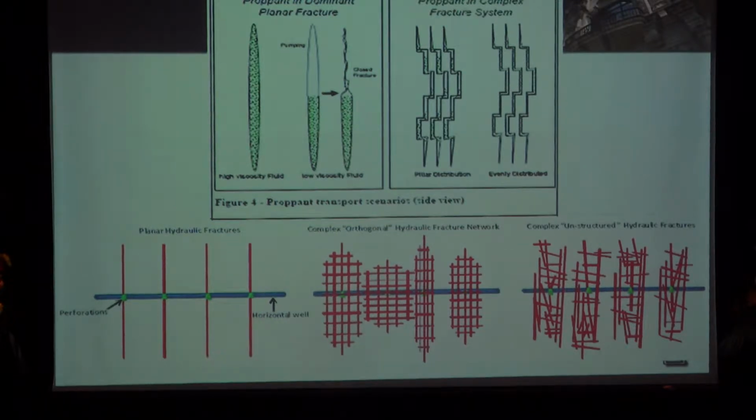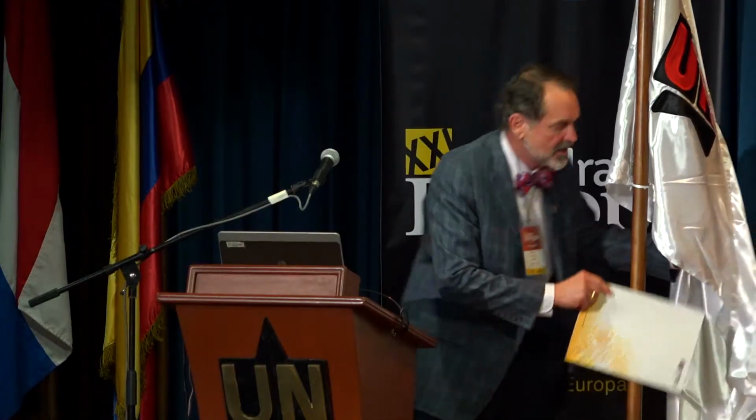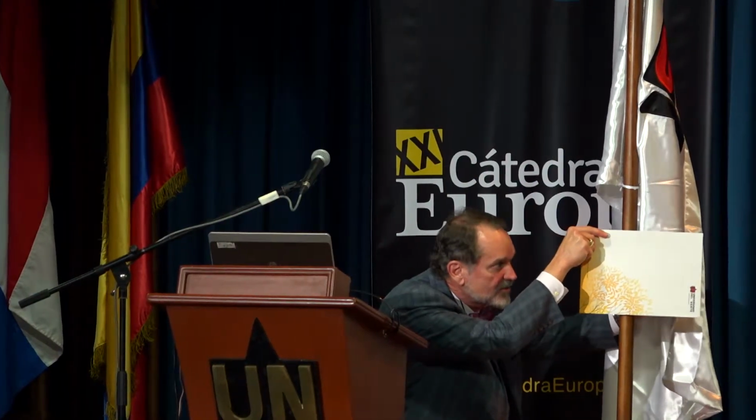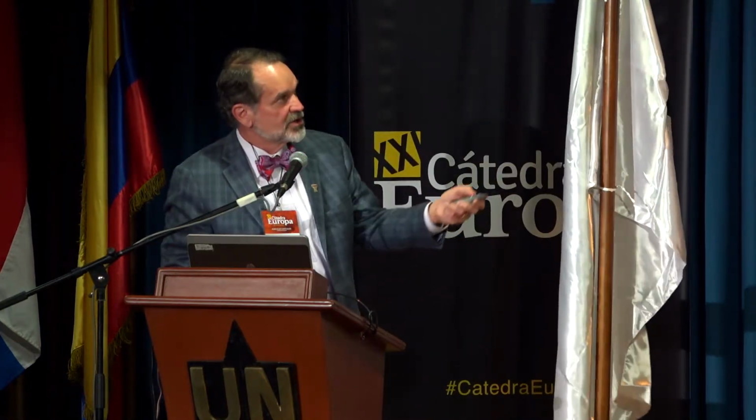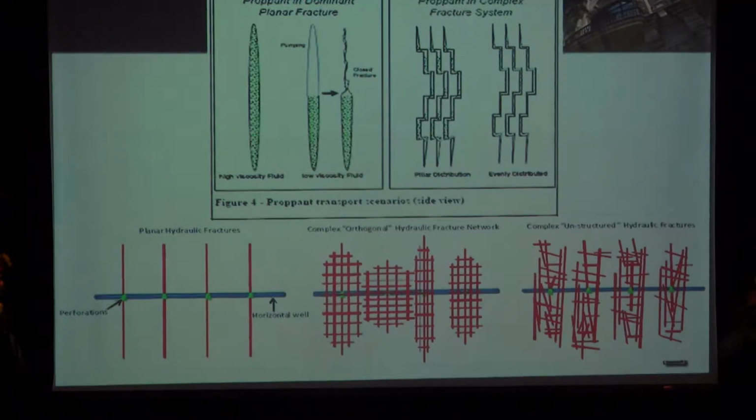Now, if I look at this fracture from the side, so instead of looking down on it, I'm looking at the frack here, these fractures, instead of looking like this, look like this here. And to make it even more complex, we have to place sand, and it has to stay suspended, because if it does not, the fracture closes back, and it's just like it was before. It becomes useless to us and does not conduct any fluids.